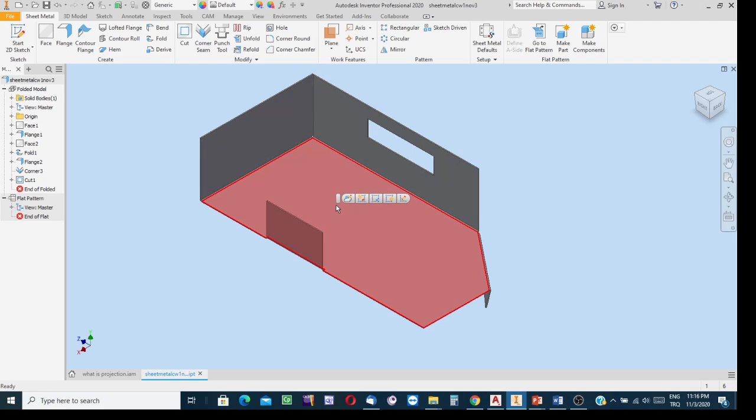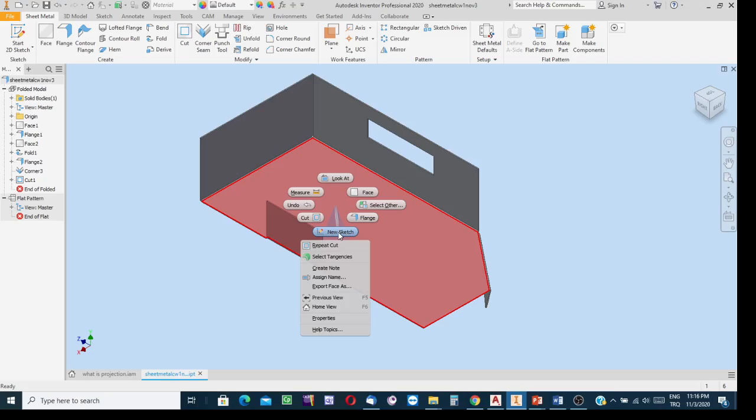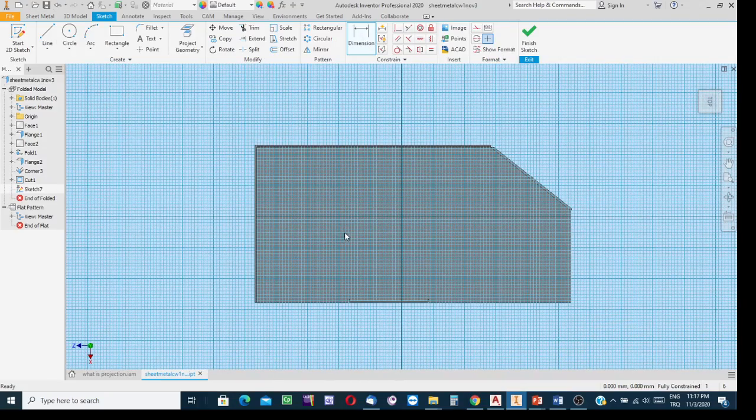Well, see, first select the surface and mark the center of the emboss. New sketch, and then using point marking facility, okay, place a point. It is the point to consider as the centroid of the surface of the emboss. Okay, apply project geometry process, have the projection of this edge, have the projection of that edge, for instance, and say that in this example we know the location of the center of the surface of the emboss with respect to those edges.